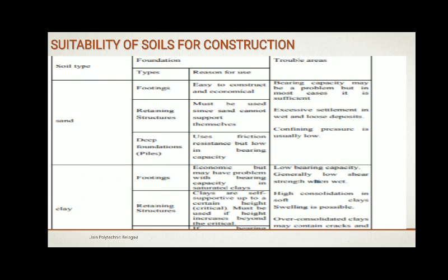Here you can see a table which is divided into 3 columns: soil type, foundation and trouble areas, which means what type of soil is good for foundations and what are the advantages and disadvantages, or the suitability of soil for construction. If you are using sand in footings, retaining walls and pile foundations, it is economical and easy to construct, but the trouble area, that is the disadvantage, is that the bearing capacity of sand is very low, with excessive settlement in wet and loose deposits.